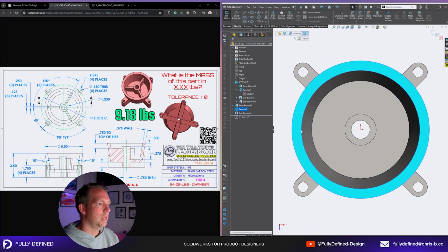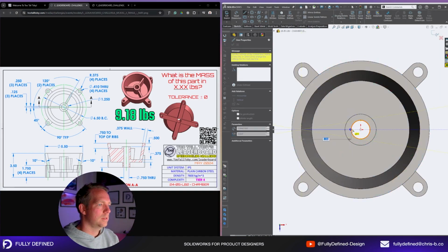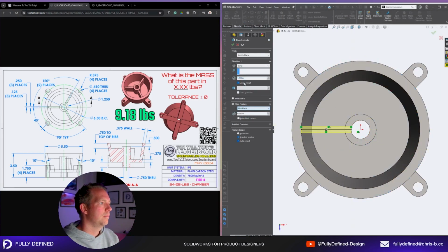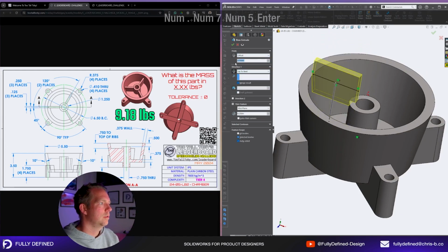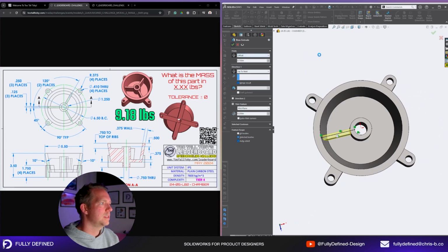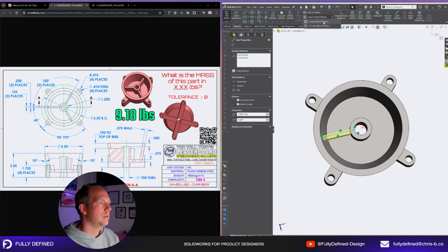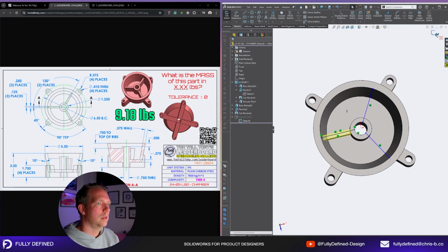and then our rib. So the rib again, from this line to this line, extruding mid-plane, going up to next, offset 0.75, but got to do 3 sketches and must be mid-plane. Yep, do that one, circular pattern 3.